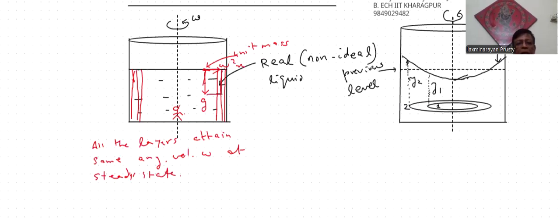like this only. And the force on the surface must be perpendicular to the surface at steady condition, because liquid cannot withstand any tangential force at the surface. So if any force is there, that must be normal to the surface. So the surface bends such that the force becomes normal here. Like this, the surface will take a shape like this, as shown here.